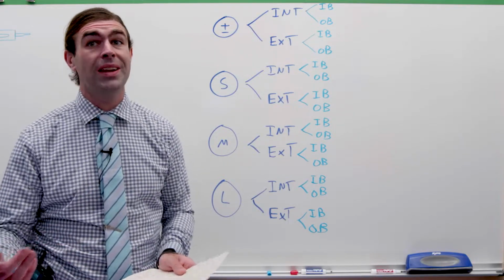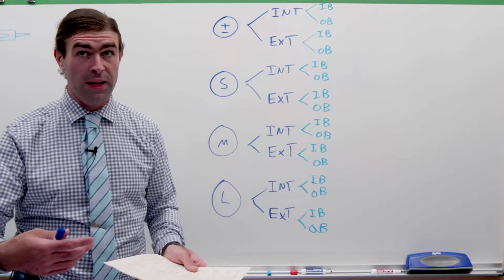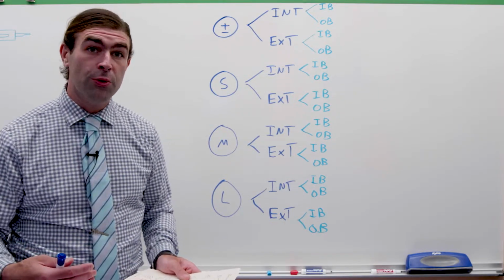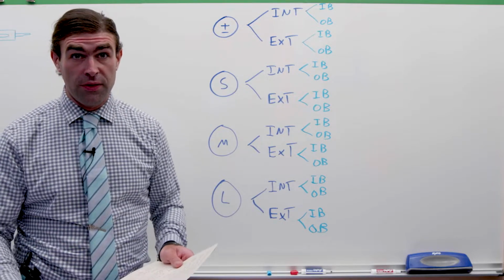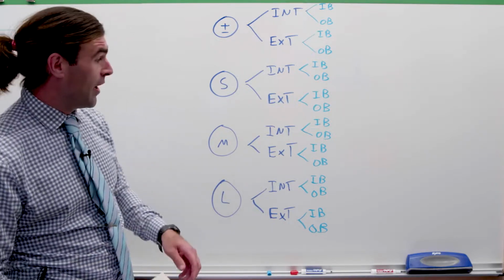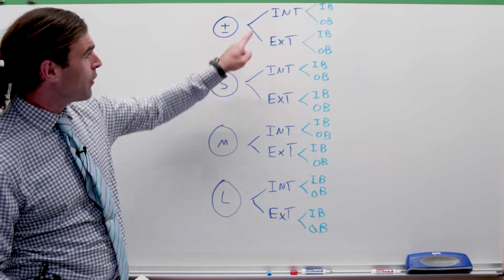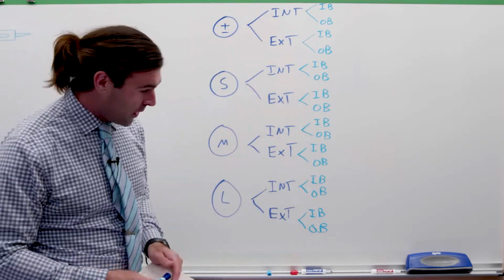It should come pretty naturally when you figure out what the inner and outer boundaries are supposed to be. And then resultant condition and virtual condition are just variations of inner and outer boundaries. They only apply with MMC or LMC. Now first, let's look at plus minus dimensions.